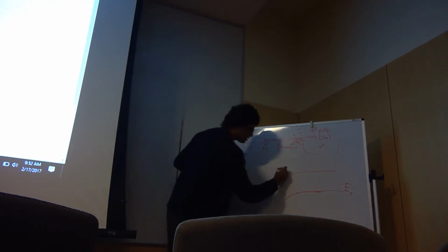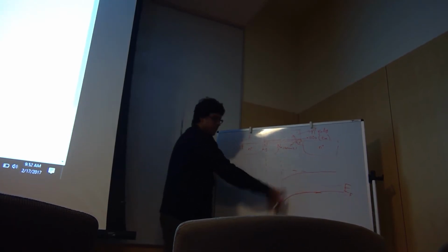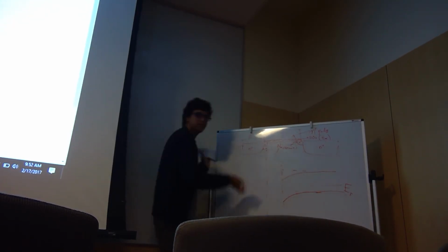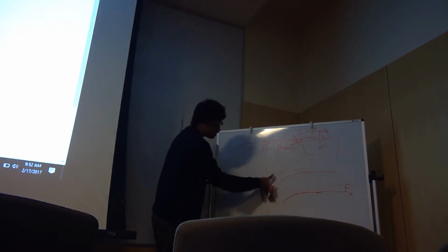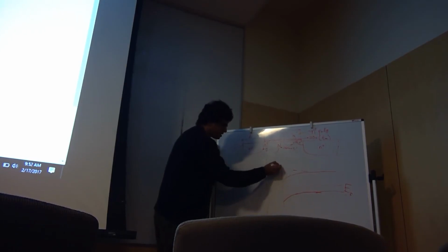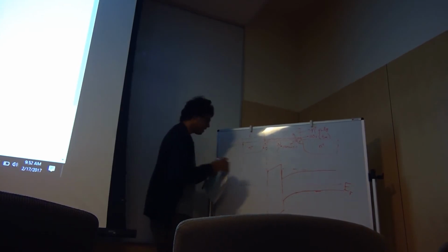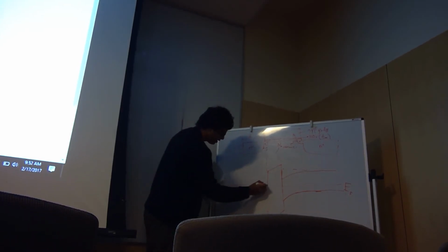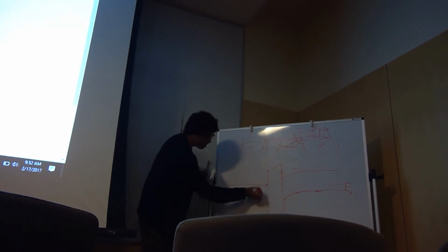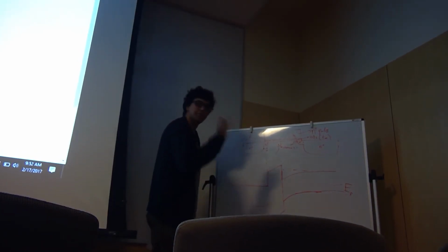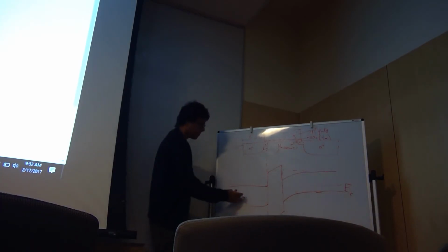This thing here is called band bending. And when you apply a voltage, this bending will change because your Fermi level will change depending on your applied voltage. There will be some voltage drop in the oxide as well, so its band will end up looking like this. And in the n-type material, it will remain like this. There'll be some bending here, but you don't have to worry about that. Assume the poly is so heavily doped that this bending is almost negligible.